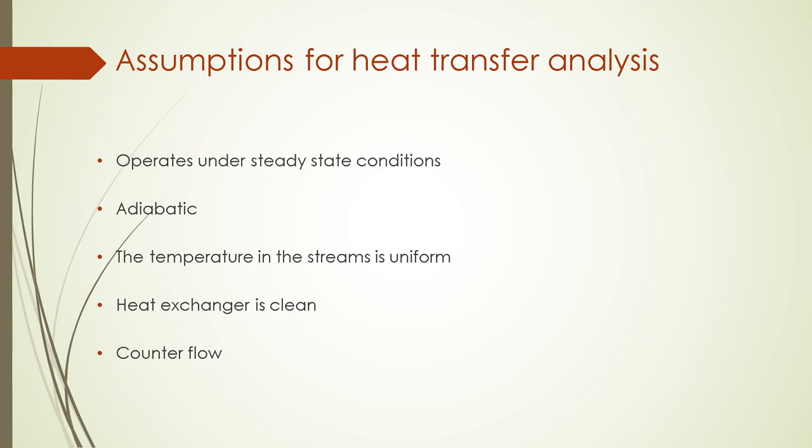To begin with the analysis, we assume that the system is at steady state, it is adiabatic, and end plates do not transfer heat. The heat exchanger is clean, so there is no fouling. The flow is fully developed and is along a streamline. There is negligible resistance. It is incompressible, isothermal, and there is no phase change. The material properties remain constant, and the fluid properties are also constant and are taken at average of inlet and outlet temperatures. For maximum heat transfer, we also assume that it is at a counterflow.